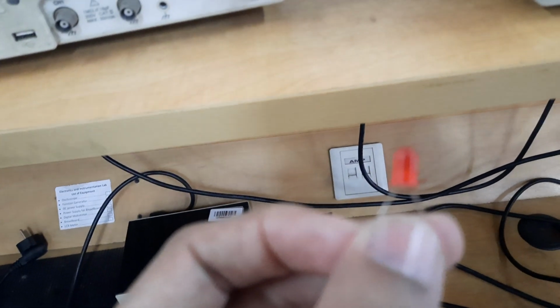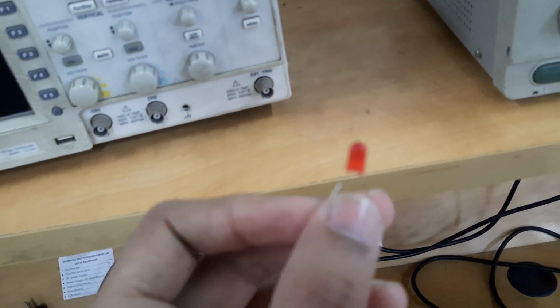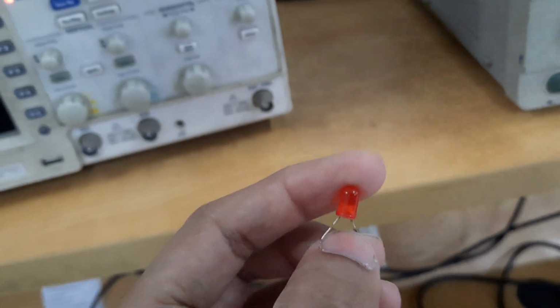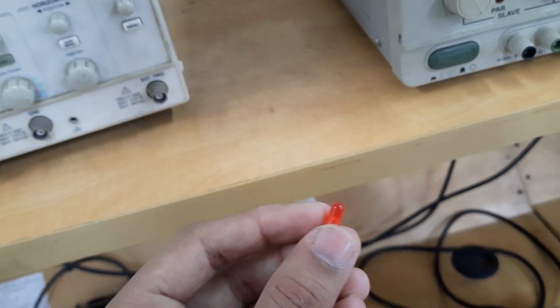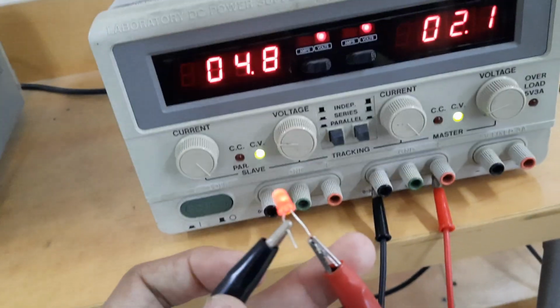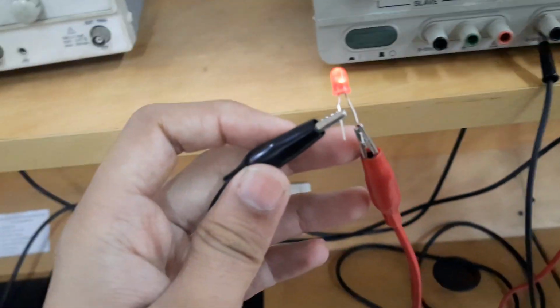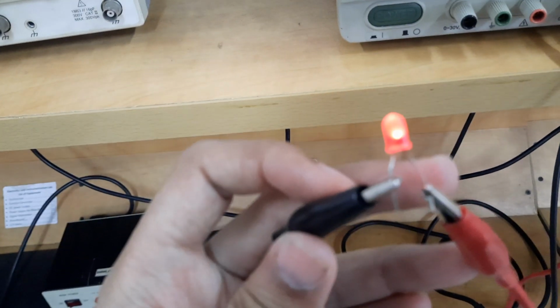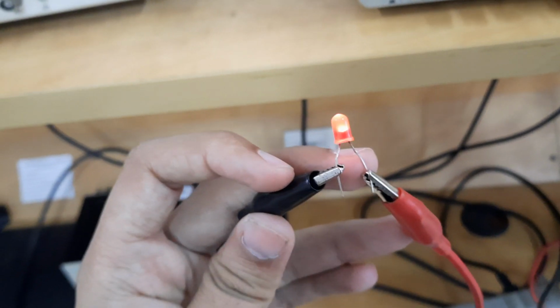As the electronic circuits in the remaining DLD portion are a lot bigger than the EDC portion, it's recommended to check every component before using it in the circuit. So how can you check if your LED is working properly or not? By simply giving it 1.5 or 2 volts. So let's give 1.5 volts. So see, you can give 1.5 to 2 volts. I have given 2 volts and the LED is glowing. Positive is connected to the same portion I told you earlier, and negative is connected here, and it is glowing, so it is working properly.